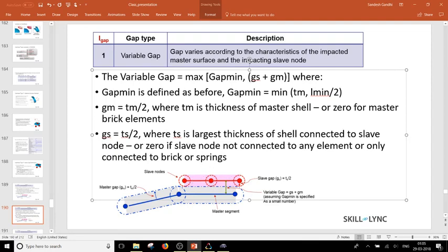In many cases, depending on the extent of the simulation that is going on while defining this contact, some part may already be deformed to an extent and the thicknesses have already reduced. If you remember, we had one option inside the shell element cards where we could say that the thickness change should be calculated during the simulation.